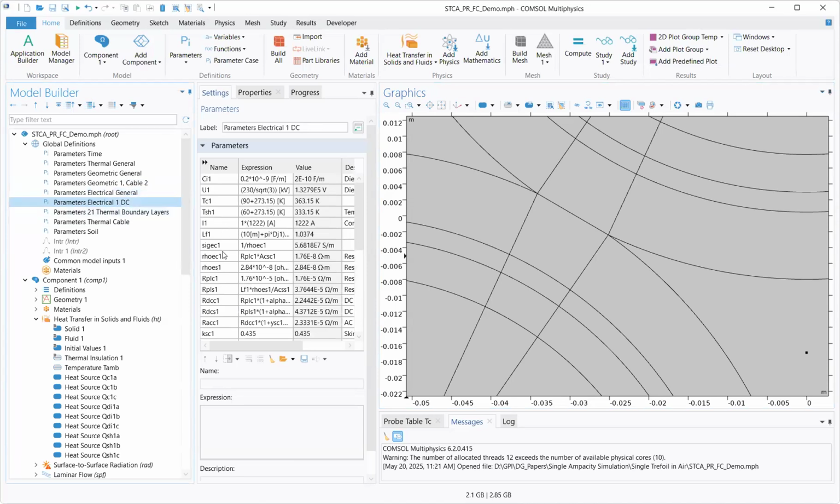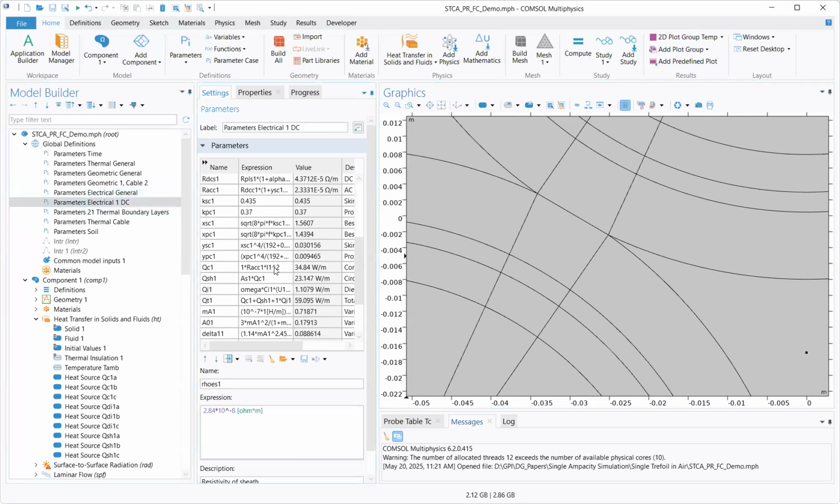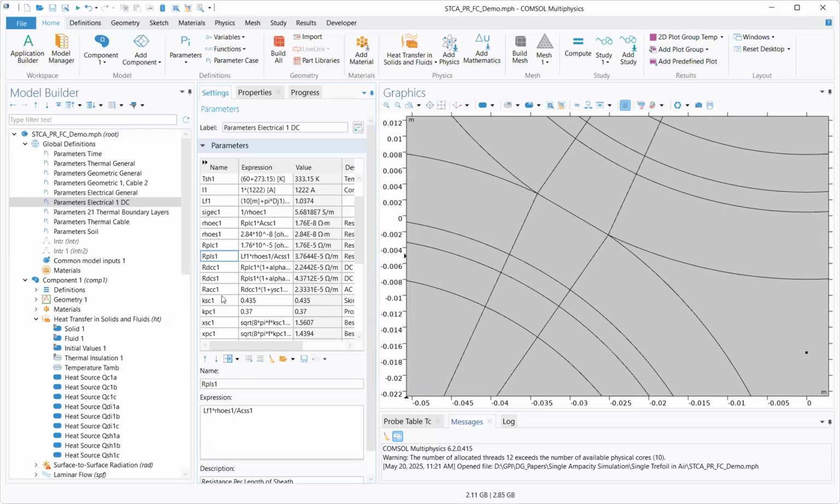So in this case, I use the IEC equations to calculate the losses in the cable: in the conductor, skin effect, proximity effect, and losses in the sheath. And I set the thermal limit to the conductor to get the value that's expected for the loss, right?